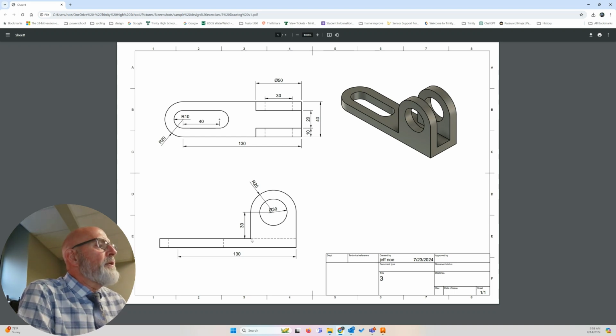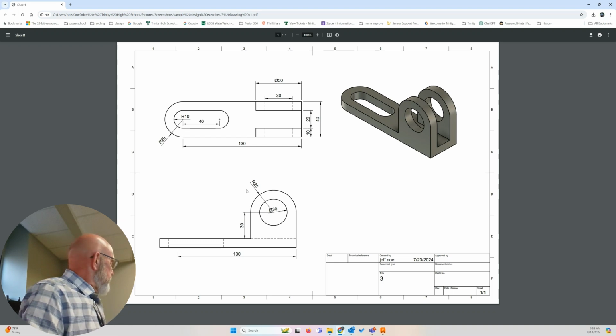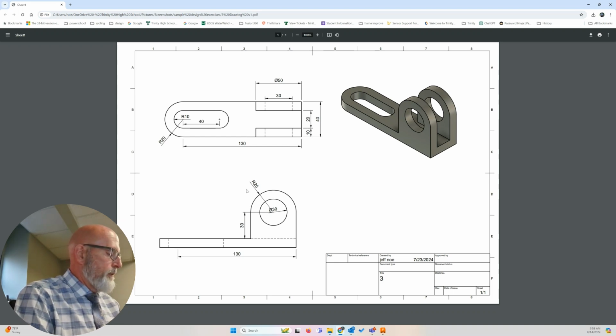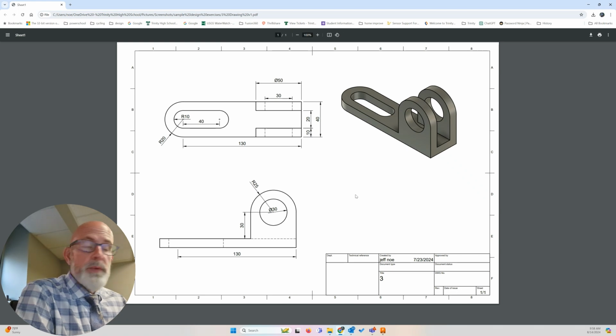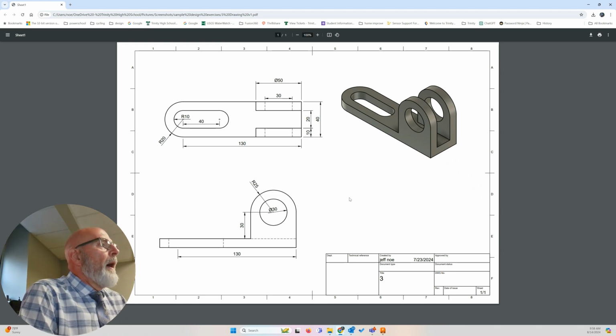I think we covered this in the last video, but if not, we'll do it again. A rectangle needs to be, if we start 10 millimeters above the bottom here, needs to be 30 millimeters up. The arc has a radius of 25 millimeters, so straight up would be 25. 30 plus 25, sorry, my blood sugar sensor is going off, would be 55 millimeters in total. How wide is it?